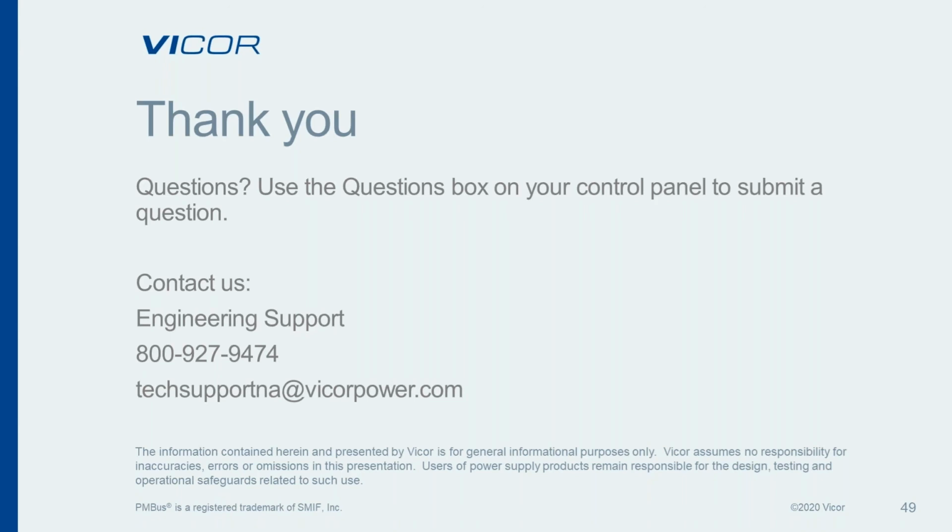That's a good question. So the Y caps are there to suppress common mode noise. And the common mode noise is generated from the switching devices to the base plate or the ground plane underneath the module. And so the Y caps should be tied to the base plate of the DC to DC converter. And if the converter doesn't have a base plate, it should be tied to the EMI ground that's underneath the DC to DC converter. And again, the Y cap should be placed with a very short loop from power lines to that EMI ground or base plate.